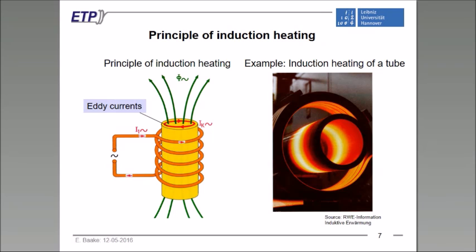The induction melting, of course, is based on induction heating. As explained several times during this EPM Academy, the principle of induction heating is, let me say, very simple. We have the inductor, which is fed by an alternating electric current and is generating the alternating electromagnetic fields. And when this magnetic field is penetrating the metal workpiece, for example the scrap, then we get the eddy currents, which finally leads to the heating up of the material or to melt the material.